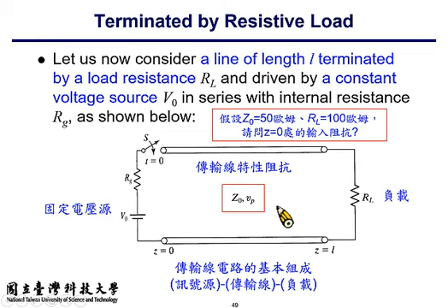Because you, as a small ant, 小蚂蚁，把自己想象一个小蚂蚁, stand in front of the long transmission line. The only thing that you can see is the transmission line placed in front of you. So the characteristic impedance of the transmission line is the input impedance you observe at this very moment, 15 ohm. Okay?